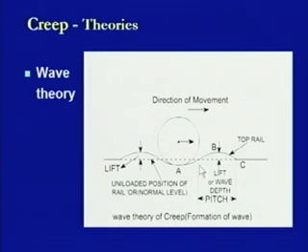So, the distance between this point and this one is termed as the pitch, whereas the total overall depth is taken from this point to this point. So, that will be the depth of the total by which this rail section is going to be deflected. And we have to look at this wave depth as well as the pitch. So, for any loaded position of the rail, this is the condition.